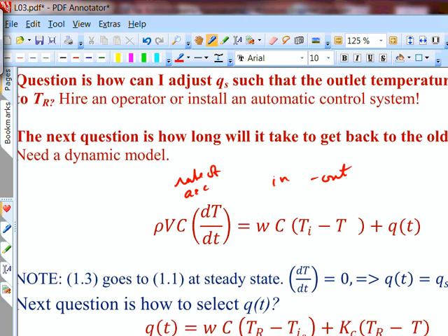So generalizing that energy balance that we did before, and I'm allowing for this Q, the heat flux into that heater, to be a function of time, because that's what I'm going to manipulate. Now, is everybody clear with that equation, or you want me to write it down and develop it? Is it all okay? All right. So that is the transient balance, and this term is called the heat capacity term, ability of water to store heat, rho V times Cp. Cp is the specific heat.